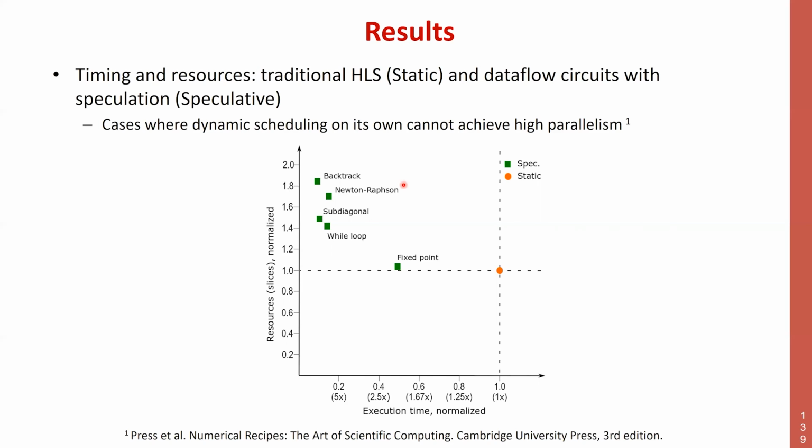And this is bad for practical situations, because you need to wait for this test and figure out if this test is true or not before you start doing the computation. So it's one of those cases that are real practical cases of code that you really need to execute, where it makes a lot of sense of doing speculation, and speculation pays off brilliantly, right? You see here is maybe even almost 10 times faster for only, because it's only 80% more area, right?